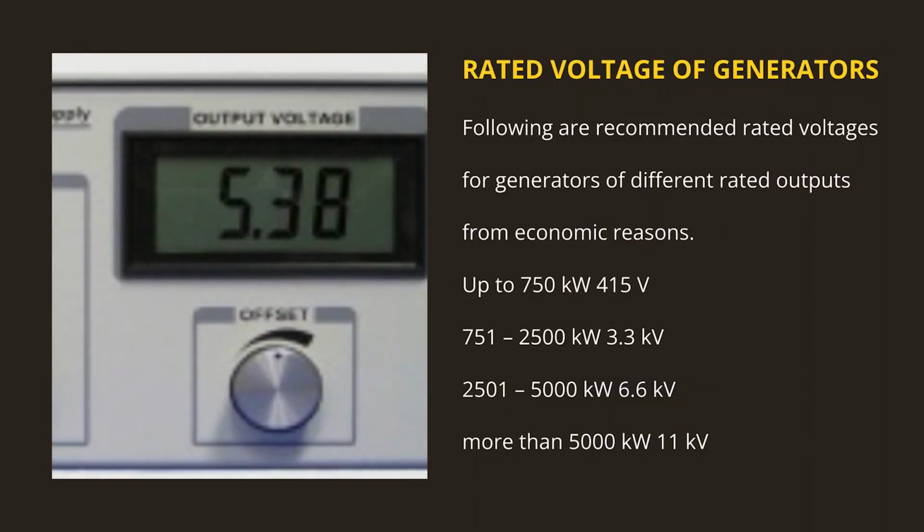When a generator is connected to the load through a transformer bank, the determination of the voltage is generally based on economic factors. Generator cost for a fixed kVA rating and speed varies with the voltage, and this change in cost must be balanced against the corresponding cost of generator leads, instrument transformers, surge protective equipment involved, etc. The possibility of load connected directly to the generator may influence the selection of the generator voltage. The generator frequency is determined by the frequency of the system to which it will be connected.